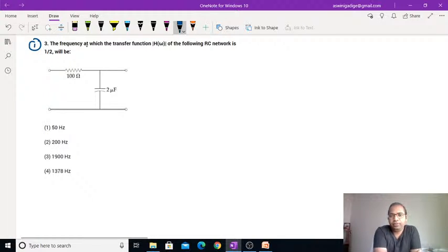of that circuit depends upon the value of these inductors and capacitors, and the output voltage also depends upon the frequencies. That means if you keep on changing the input signal frequency, then you will get different voltages, fine. So that is the difference between the resistive network and the reactive network.